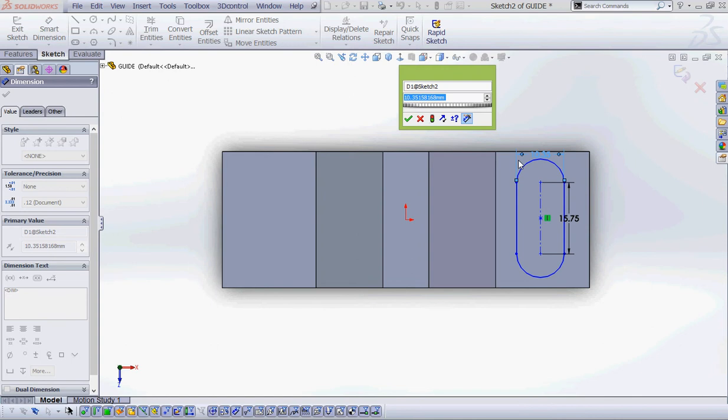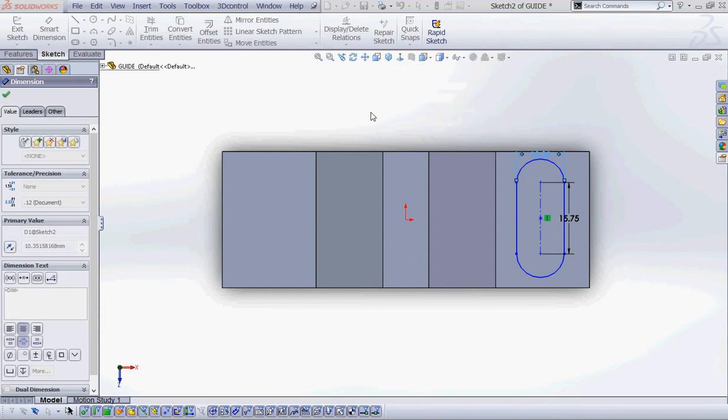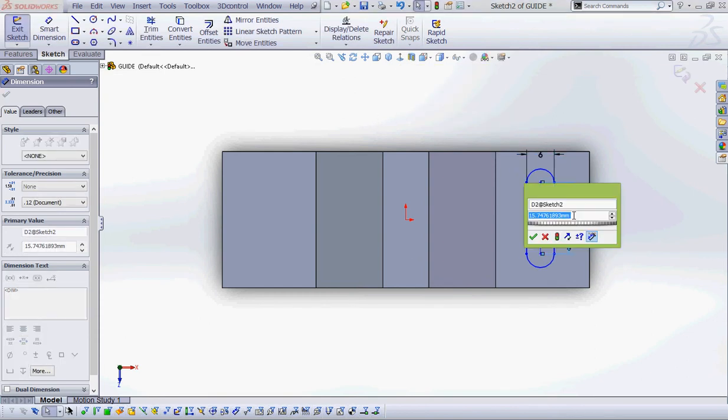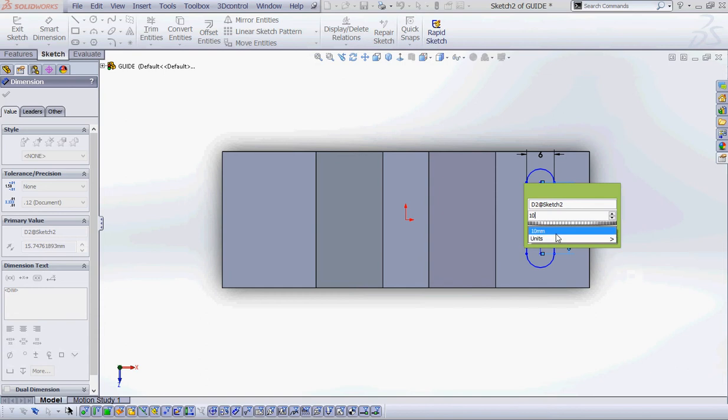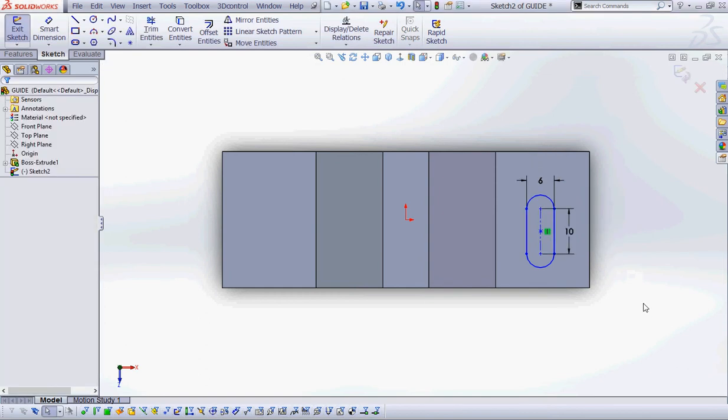Okay, so if you go to options, which is right here, and you go to sketch, do you see right here where it says auto rotate view normal to sketch plane? That means that every time you set a sketch, it will automatically put you in a plan view. Now if you want that option as you're working every time, add that to your flight checklist, that you set that option, right?